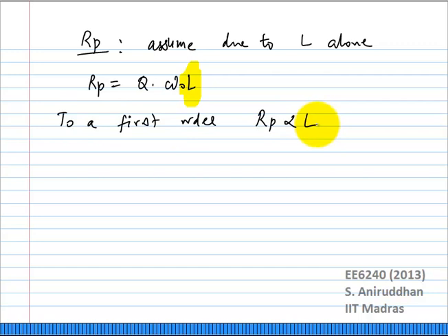Now, how do you proceed? For a given current, you will always have a current consumption barrier, right? You can assume that your VCO needs to be designed with a certain maximum current in mind. Assuming you are going to use all that maximum current in the VCO, what that means is, to get the maximum amplitude, you need to maximize RP, right?